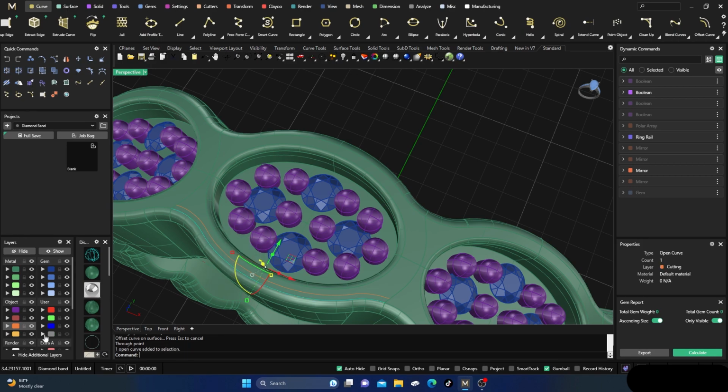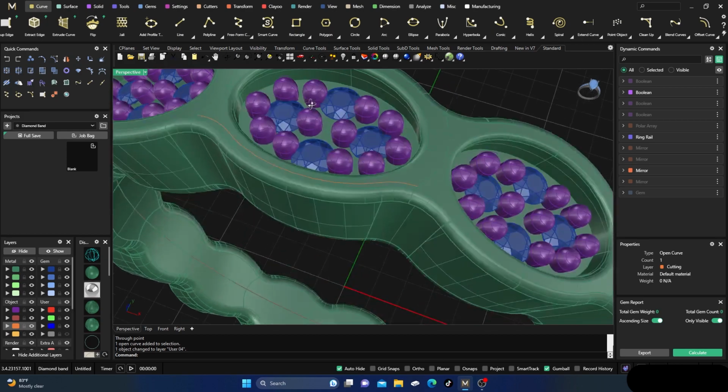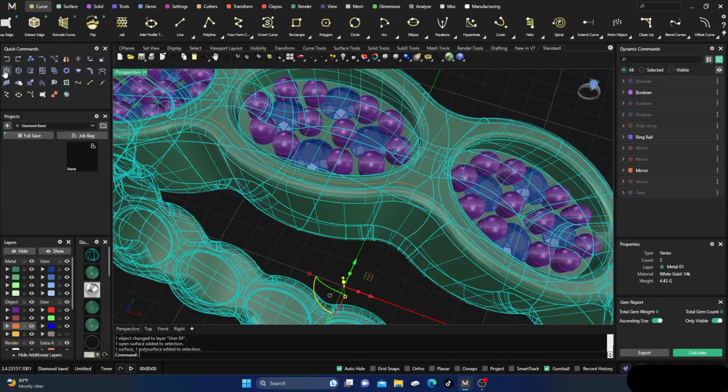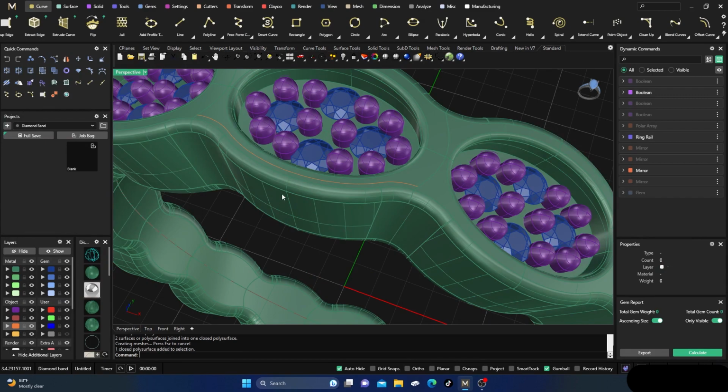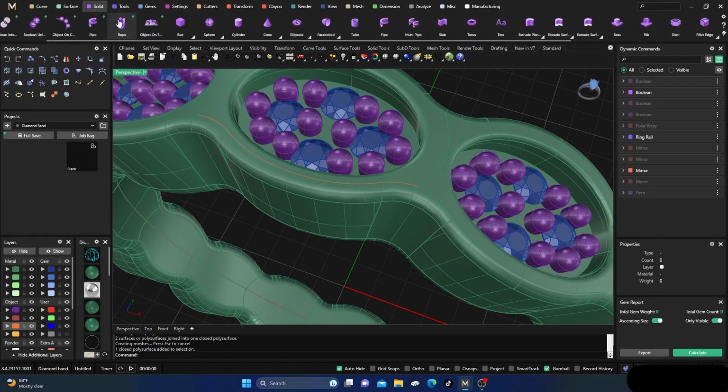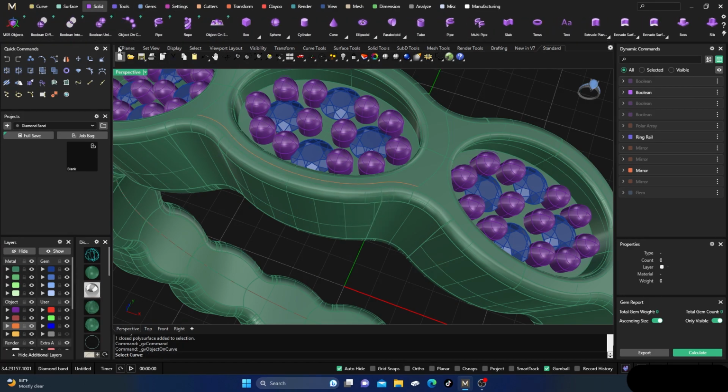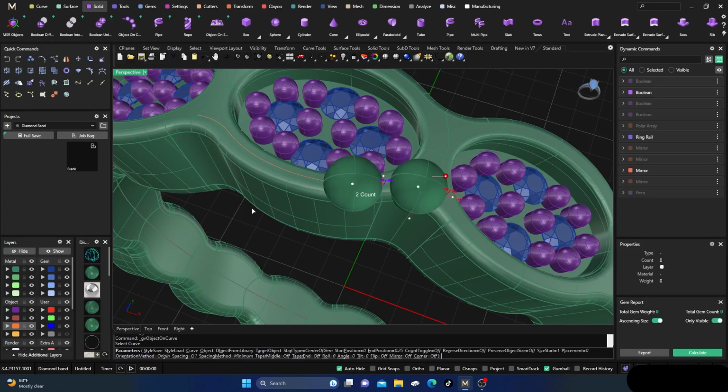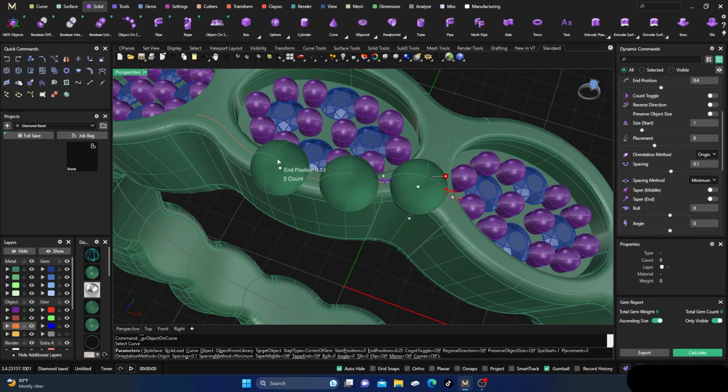Okay, and then we'll keep this one. We'll take that curve and turn them to gray just in case. So I have this here, right? That surface is still extruded, so I'm just going to grab all green so I know that it should be all back together again, and we are. So I'll grab that curve there and go to my Solids and go to Objects on Curve. So I'm going to select curve, this one here, hit enter, and we have our little balls out here,